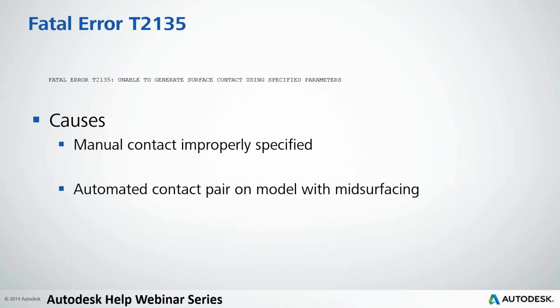So it's important to go in and manually modify those contact pairs so that they're edge to surface now instead of surface to surface, because the surface, most likely that was mid-surface, or maybe if you're thinking of a box, now we've just got a flat plate. We're missing 4 of those surfaces now because the part has been idealized as a mid-surface.